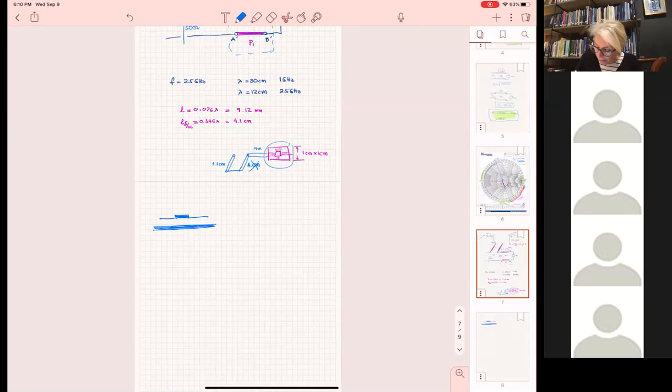And then, in 3D, it will look like this, all right? So the difference between a microstrip and a coplanar waveguide that looks like this. A coplanar waveguide has all of the metals on one side. And when you look on top, it's going to be like this.